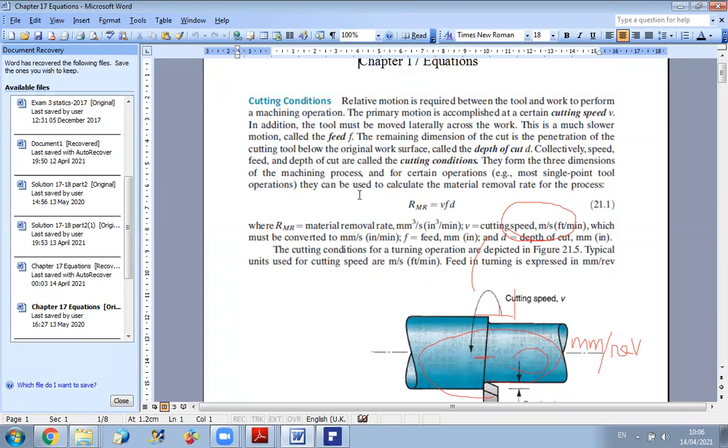If you have watched the PowerPoint recording, you have also seen, for example, in milling and drilling, not single point tools but several point tools. In this case, you have several faces doing cutting operations. For the removal rate, the unit will be millimeter cubed per second. It is a volumetric rate, and it expresses the rate of metal removed during the operation.